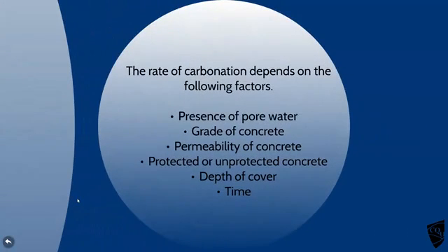The factors that can have an effect on this carbonation are the presence of water, the grade of concrete used, how permeable your concrete is, which comes into workmanship as well. I mean, have they actually vibrated the concrete when they cast it to get all the air bubbles out of it? Whether it's exposed or protected, unprotected concrete, how deep the cover is, how much concrete is there before you get to the reinforcement, and the time. Which, as I say, in Europe, we have 40 mil cover, millimetre a year. The time is 40 years before you should fail.